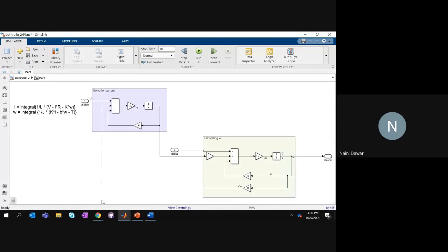Yes. So Simulink is a platform in which you can basically design with simulations. In this particular example, I simulated the model and could see the result. Since I was using my existing DC motor's parameters from the data sheet and putting in the values directly, I was able to simulate the behavior and see how angular speed changes according to different input voltages.